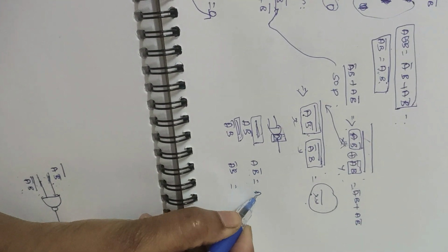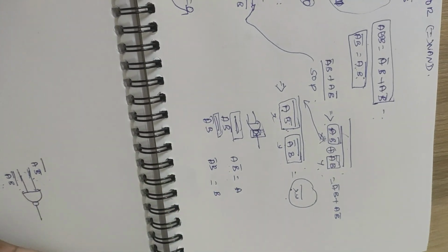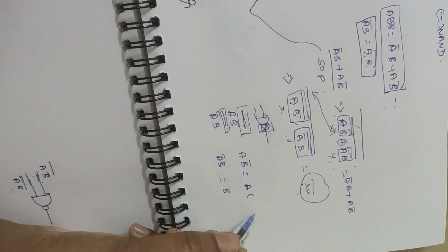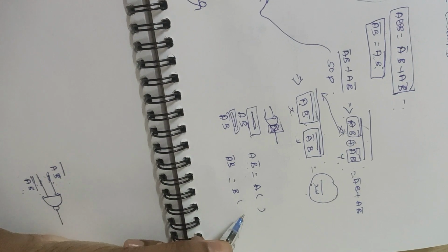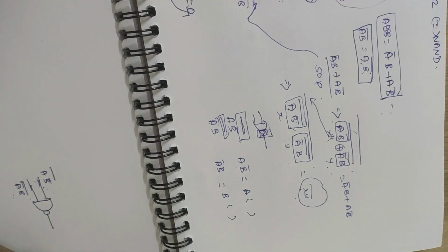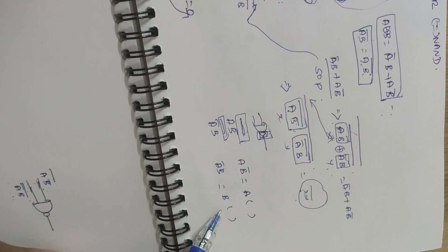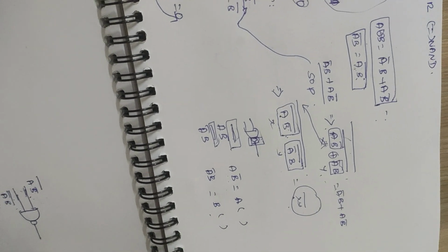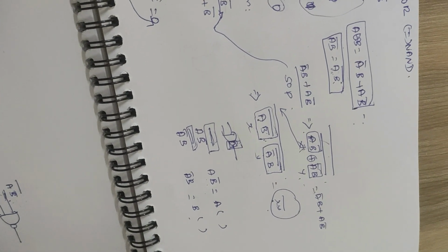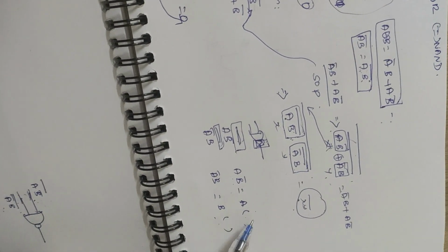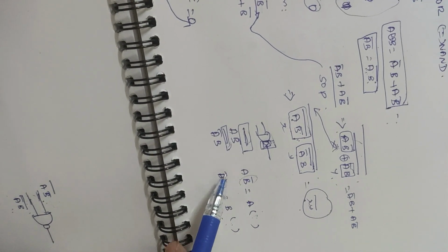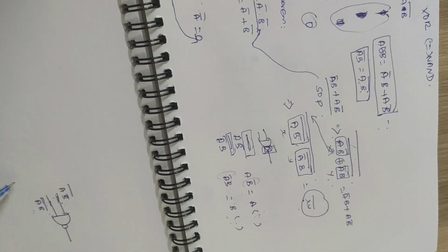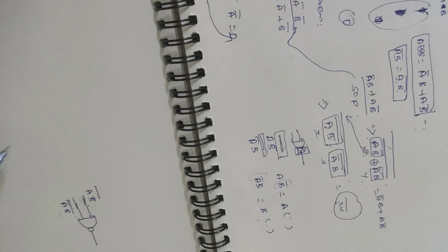Generally what we will be having as a ready-made input will be A and B, that is our ready-made input. So here if you need this A B bar using here, and here you need A bar, right? So here you need B bar and here you need A bar. That is what you need for this particular A. So what I am trying to tell, if you have used different NAND gate to implement this particular NOT gate, it will become again another one NAND gate for here. So 2 already, again another 2, so it will be 5 gates.